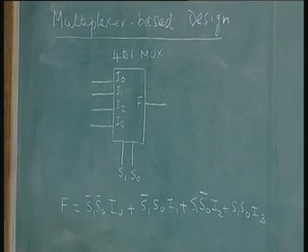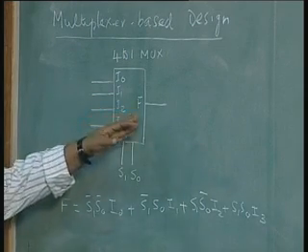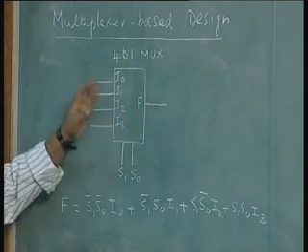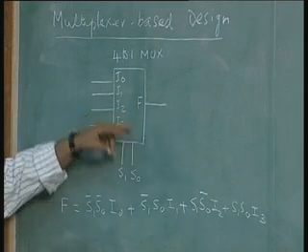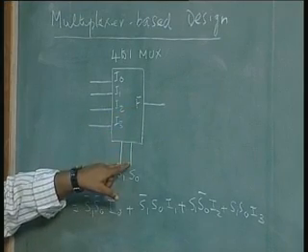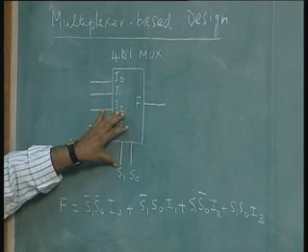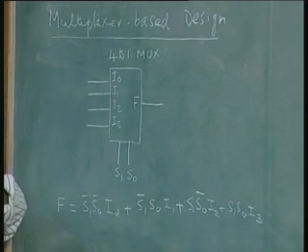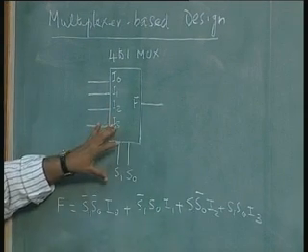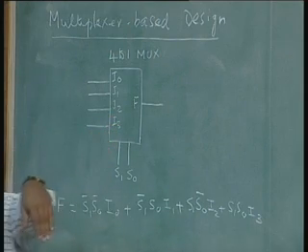This is a multiplexer which selects from a given number of inputs one of the inputs as the output, and the output selected depends on the selector combination. Now, I can use this component to design a combinational logic. Now, this is not a gate approach, but it uses gates because you know that a multiplexer cannot be built without gates.